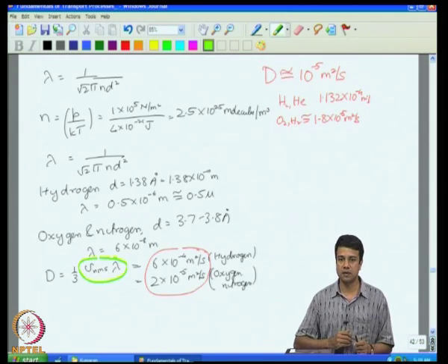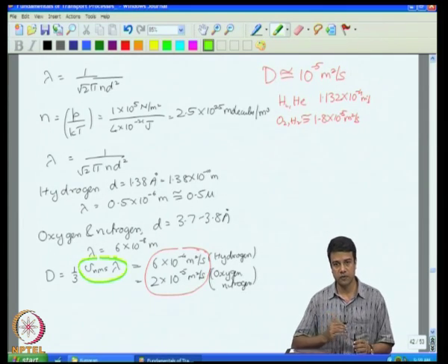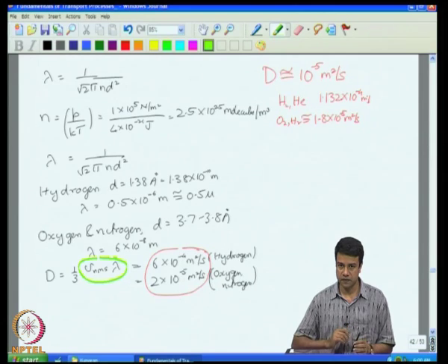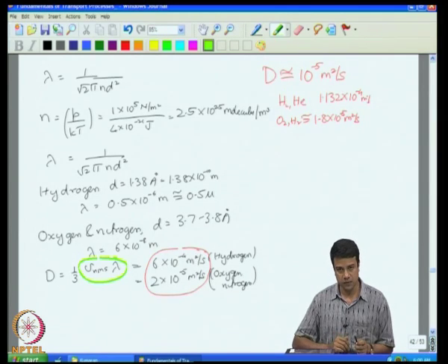Momentum diffusion does not require the motion of molecules physically. It can take place due to the forces exerted by one molecule on another. So, momentum diffusion is faster. Thermal diffusion depends upon the mechanism by which it takes place. In liquid metals, it is very fast because of the transfer of energy due to the electron clouds around the molecules. In the case of organic molecules, it is very slow. There is a whole range.